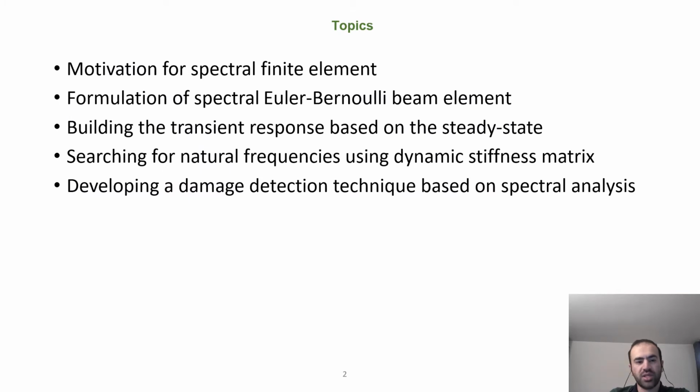In this presentation, I'm going to talk about the motivation behind the spectral finite element method, and we will see how we can apply it to solve the problem of vibration of Euler-Bernoulli beam elements, and we will see how the result from the spectral analysis is incomplete and how we can build the transient response based on that.